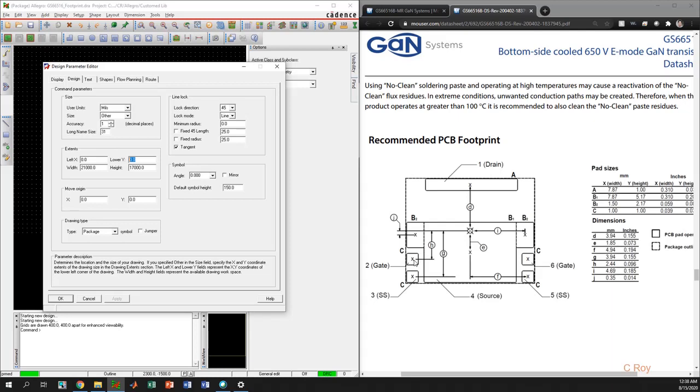And it is also lower than the origin. So both x and y coordinates for this pad will be negative. Now, if our origin is on the lower left corner, we don't have any option to put negative coordinates. That's why I want to move this origin to somewhere in the middle.